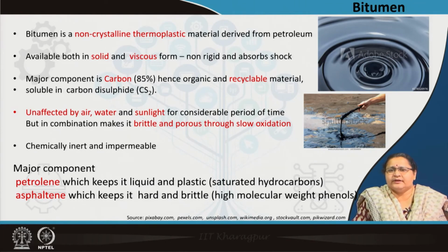It is soluble in carbon disulfide, that is CS2, and yes, it is a recyclable material. It is a very impervious material, it can be continuously used, it is weatherproof, it can sustain temperatures, it can sustain shocks. So, all the qualities we had discussed for a damp proof membrane are with bitumen, and hence